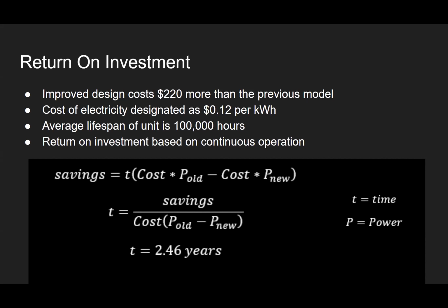Was there any opportunity to slow the fan down to aim for a lower flow, and then you reduce your power consumption by operating the fan a little slower? Yes, sir, there was. Right now, to achieve that 90 feet per minute, we're operating at a flow index of 8%, which means the motor's operating at 8% of its full capacity.